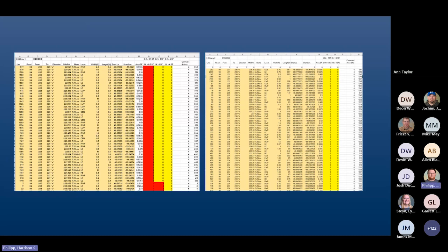The reason I had the red and yellow highlighted areas is because there were way too many spalls to put on our set of plans. I guess due to the poor road condition, there were just way too many. And part of that reason is the way we outline the spalls in the software. As you can remember, the previous slide, there was a lot of small highlighted areas of spalls. We could have reduced that to 1 larger spall replacement, which we should have done, but we just didn't know how to use the software right away.